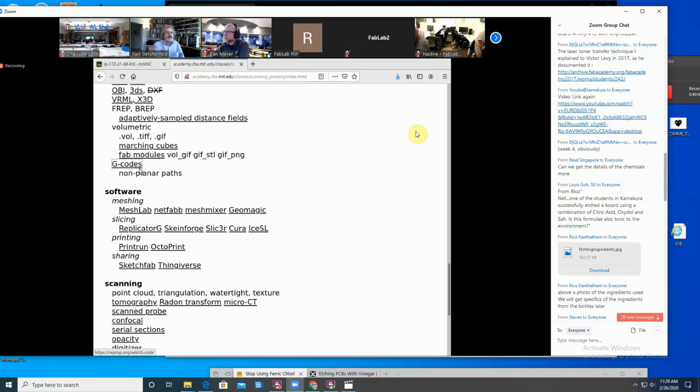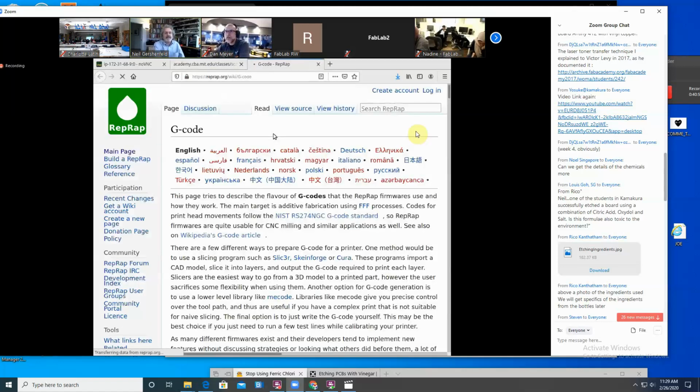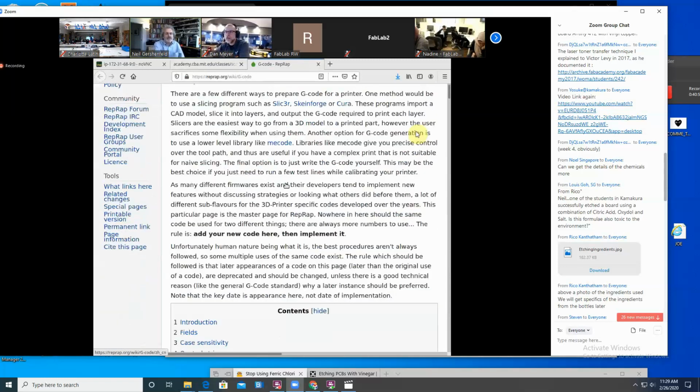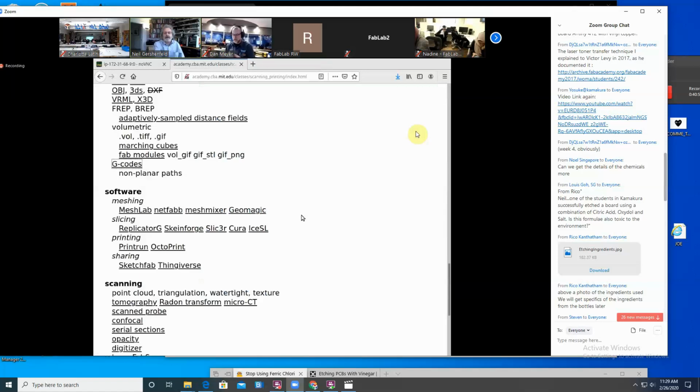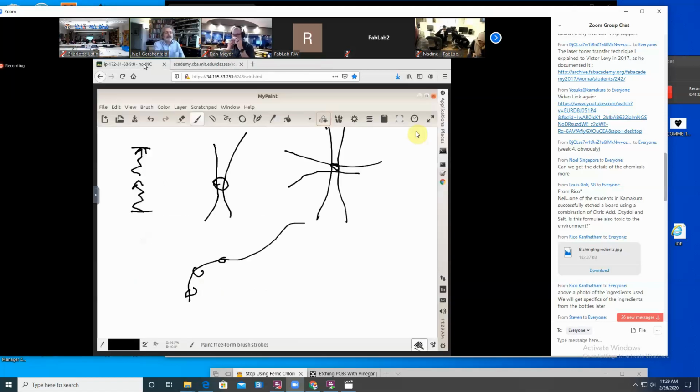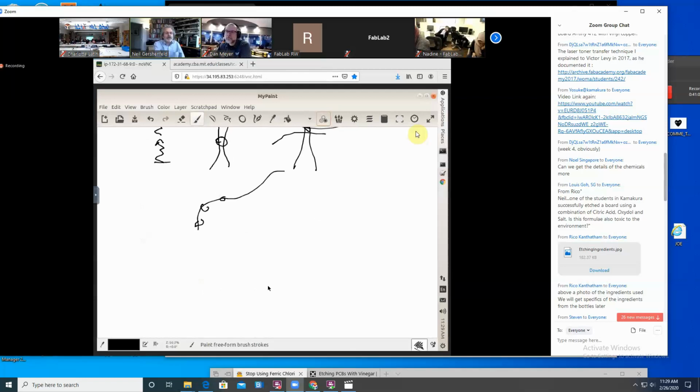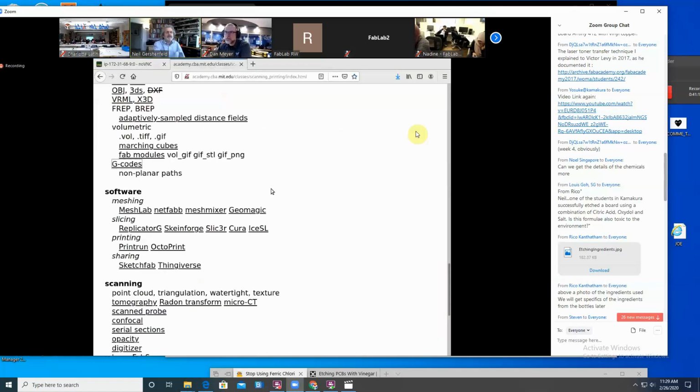And then most in particular of the DIY style printers use G codes, which again is an ancient format, but a commonly supported one. One of the interesting things about using G codes is normally in 3D printing, you print on layers, but the G codes can go in any axis. And so there's interesting experimental work with printing objects, not just by printing horizontally, but by using all three axes to make smoother surfaces and print more quickly. That's not yet well supported in the software workflows, but the G code can support it.